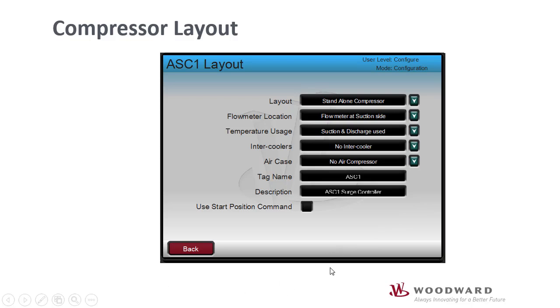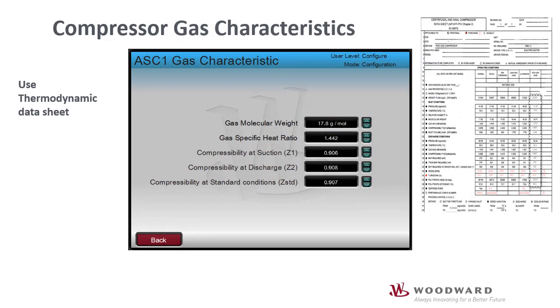Now the next portion is the gas characteristic. For the gas characteristic page, we need the compressor thermodynamic datasheet. Basically, we are interested to know based upon which operating condition is selected. Remember, we can only feed one operating condition at a time for the Vertex. And this can be fed while the unit is in shutdown and in IO lock. So we have chosen the normal condition after discussion with the plant operators.